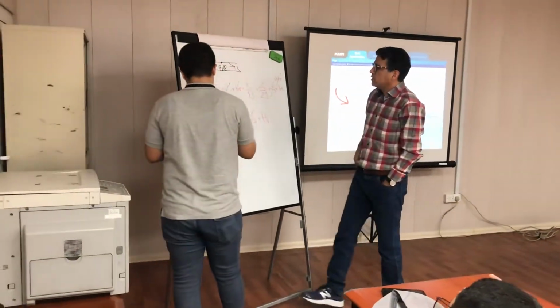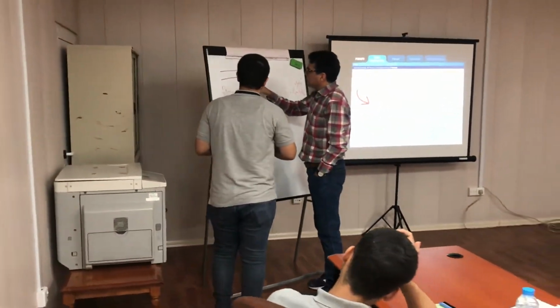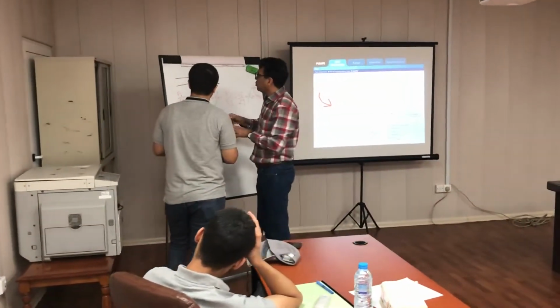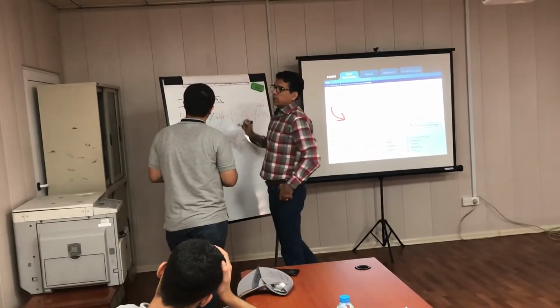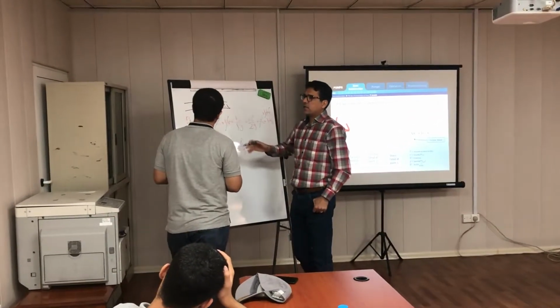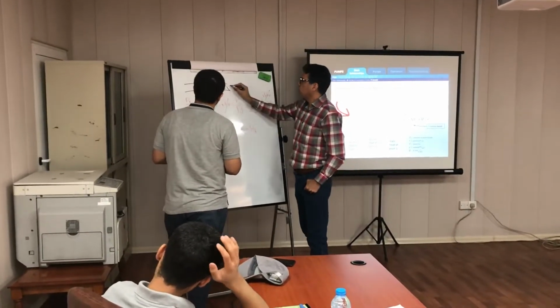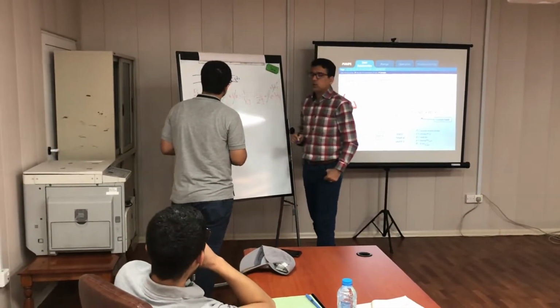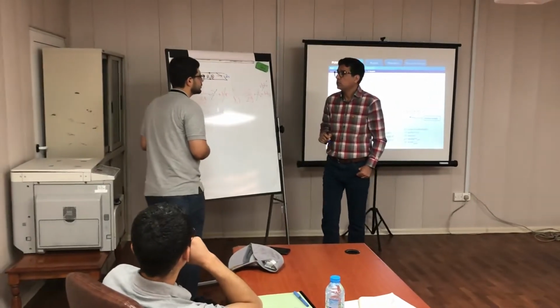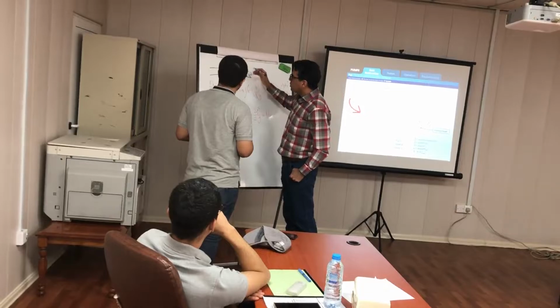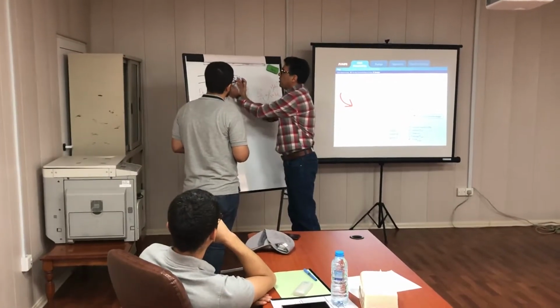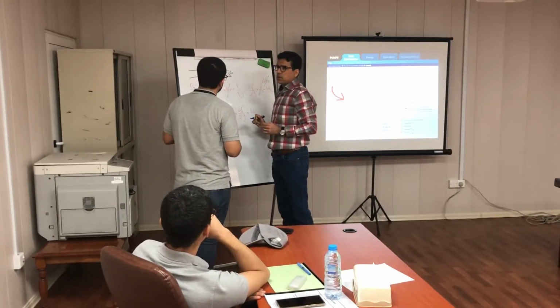Okay. The velocity: if at this point we have Q1 here, what about the Q here? Is Q2 equal, less than, or more than Q1? We have to discuss the Q. No, it's equal. If Q2 is a little bit less than this one, that means you have accumulation around here.